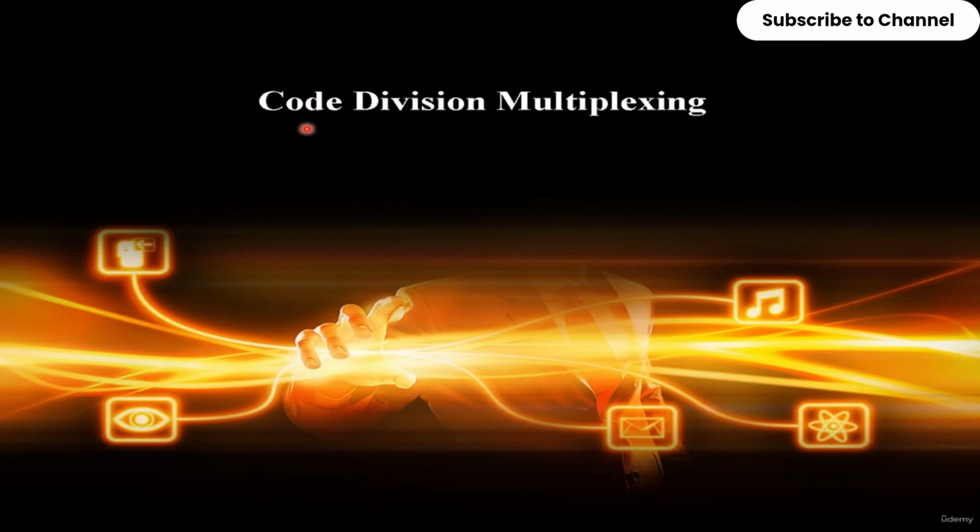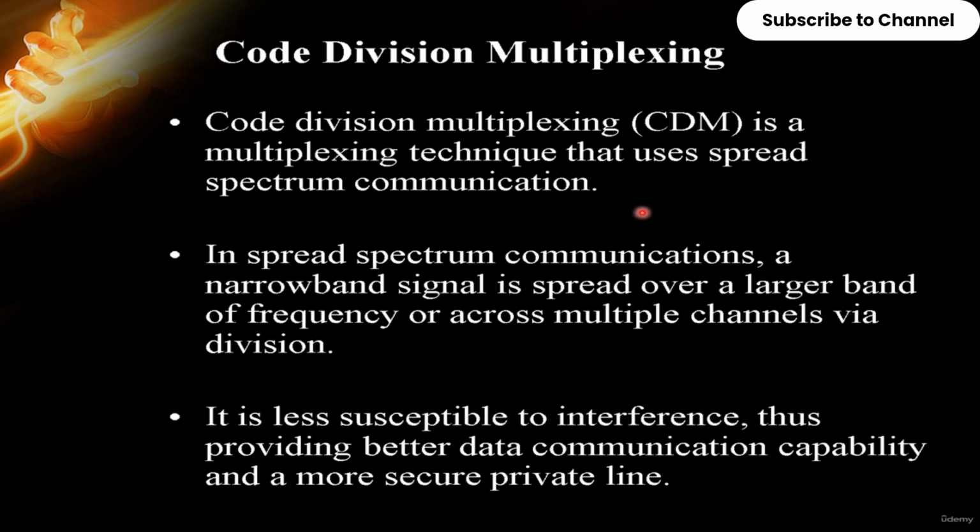Hi, in this lecture we are going to discuss the basic understanding of code division multiplexing. Code division multiplexing is a multiplexing technique used in spread spectrum communication. In spread spectrum communication, a large bandwidth of frequency is used across various channels with narrowband signals. Here the interference is very low because different codes are used for different channels, and it is more secure compared to other multiplexing techniques.